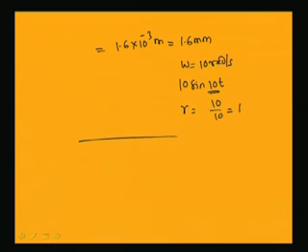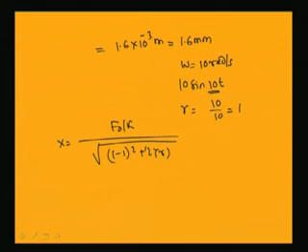can be given by, or you can give your x equal to f0 by k, root over 1 minus r square whole square plus 2 zeta r whole square, with r equal to 1. So, this damping factor only will limit this thing. This is coming to be 14.142 mm. In the third case, you can find x will be equal to 1.5 mm.